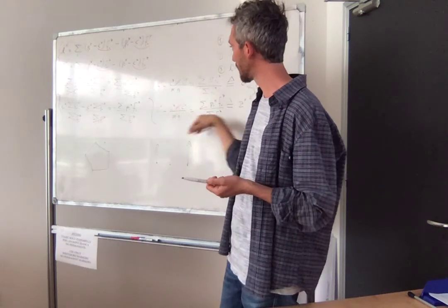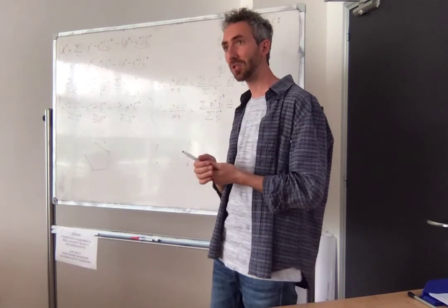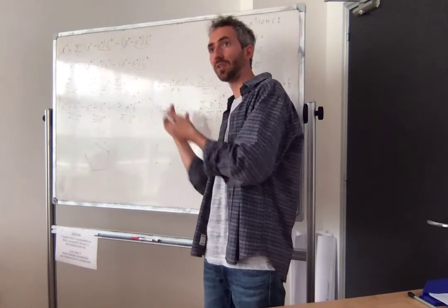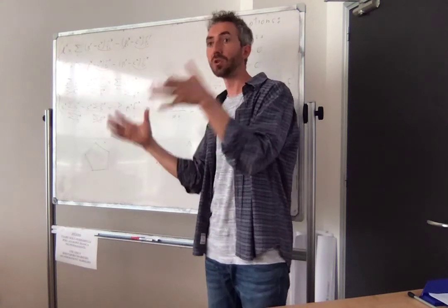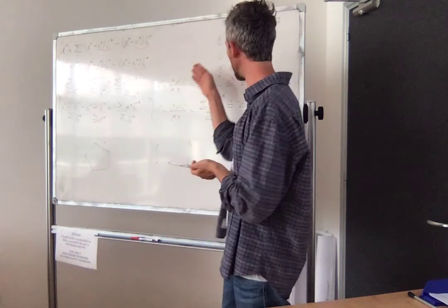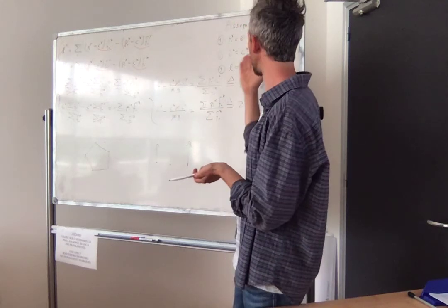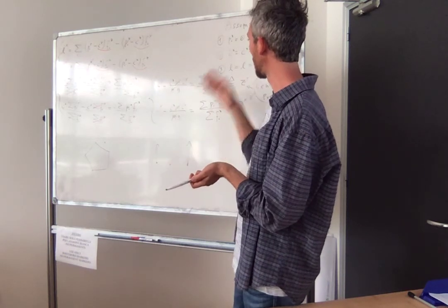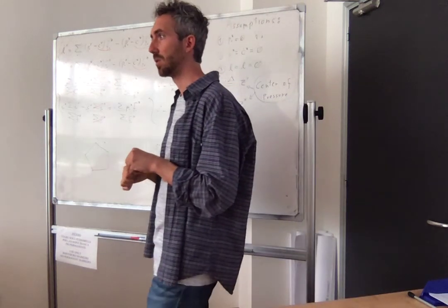And these equations here are actually equivalent to the linearized equation of an inverted pendulum. But here, instead of deriving them from the inverted pendulum equation, we have derived them from the equation of a single rigid body, which I think is closer to the dynamics of a multi-body system. And we have seen under which assumptions these equations make sense, which are basically the assumption of walking on a flat ground with a constant center of mass height and with zero angular momentum. Questions?